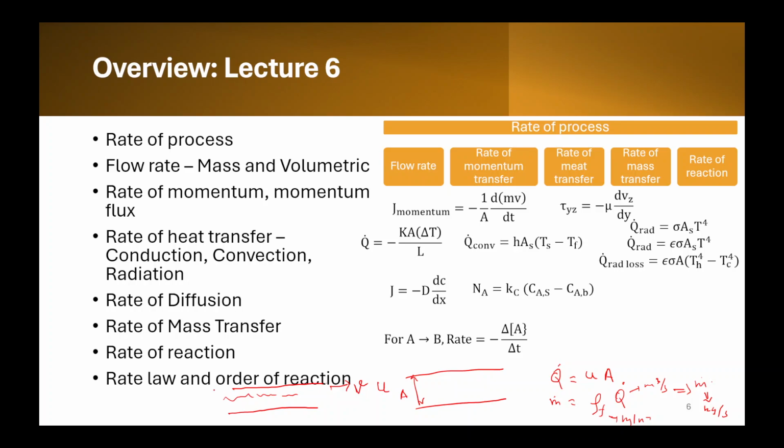With a velocity v, or some force is applied here, if we can say that. So this is moving. There is some fluid between, and this is stationary. This is not moving. So there exists a velocity gradient. However, this is moving, so it will take some fluid along with it, some packet of fluid along with it. But the velocity keeps on decreasing as we go down. Why does this happen? It is because of the existence of viscosity. Viscosity is an intrinsic property of a fluid which resists the flow. So because of the existence of viscosity, there exists a velocity gradient.